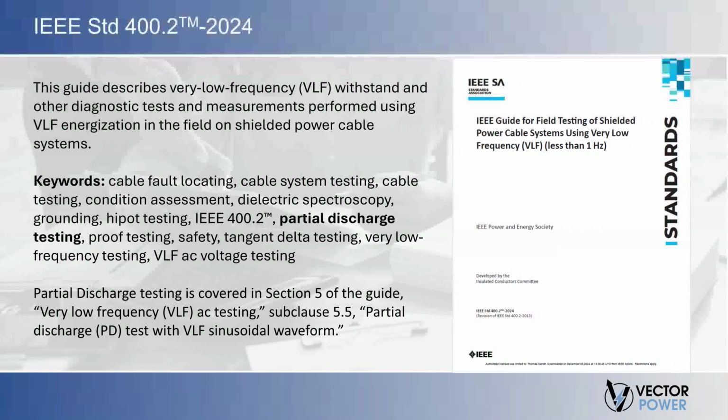How about we now talk about what resources we can turn to better understand the complexities, process, and analysis of partial discharge. Among these, we have the IEEE standard 400.2-2024. This guide describes very low frequency, or VLF, withstand and other diagnostic tests and measurements performed using VLF energization in the field on shielded power cable systems.